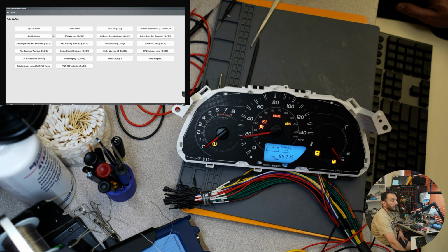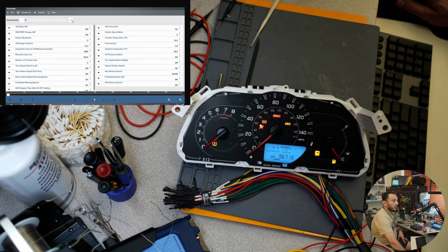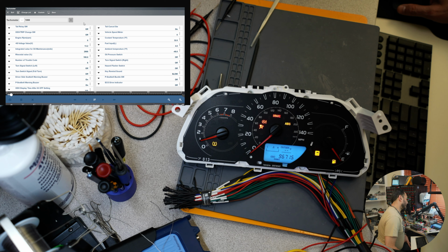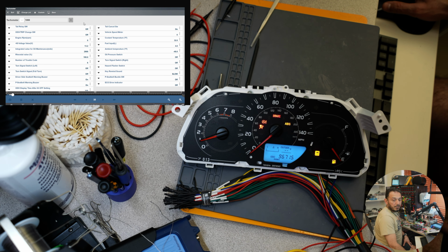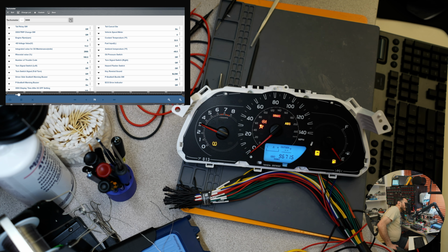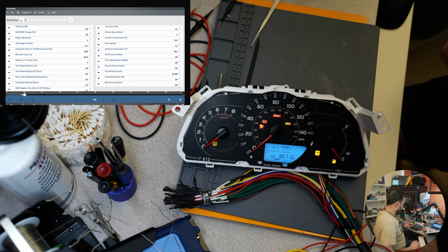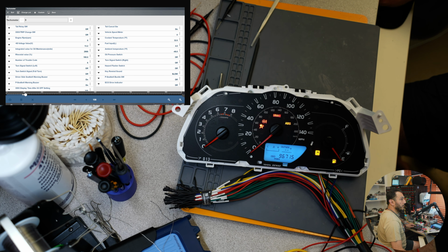All right, so now let's do the tach. And the tach is going to go to 1,000 RPMs. And I see it's actually perfect on 1,000 now. So let's go 2,000, 3,000. I think it's a little off in there. Yeah, I think it needs to go down a little bit. So let me adjust that.